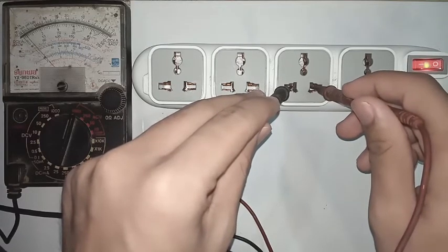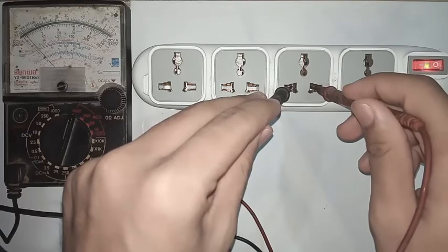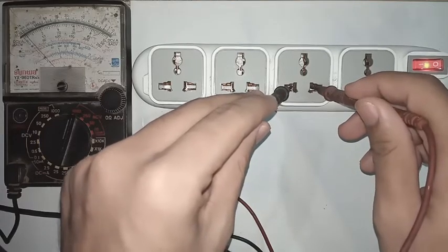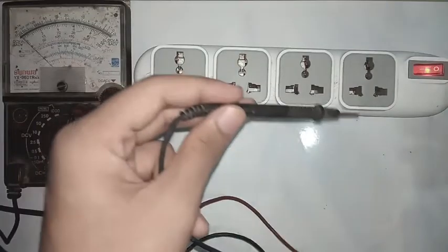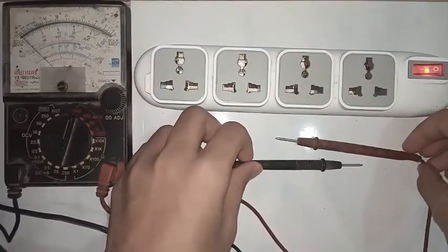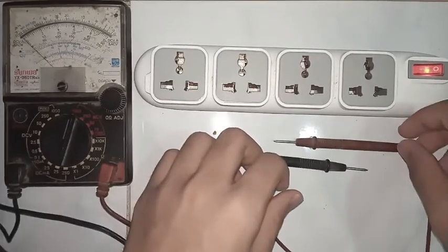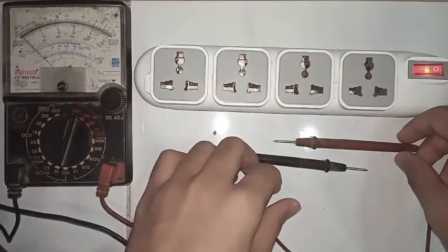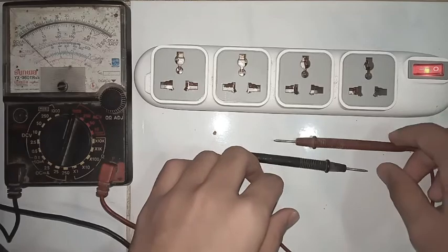Be reminded, for measuring the voltage of an element in an AC circuit, we need to connect the multimeter in parallel. Also, if we use the multimeter to measure the voltage in an AC circuit, we will get the VRMS value. So to get the V peak value, we must multiply the VRMS value by the square root of 2.